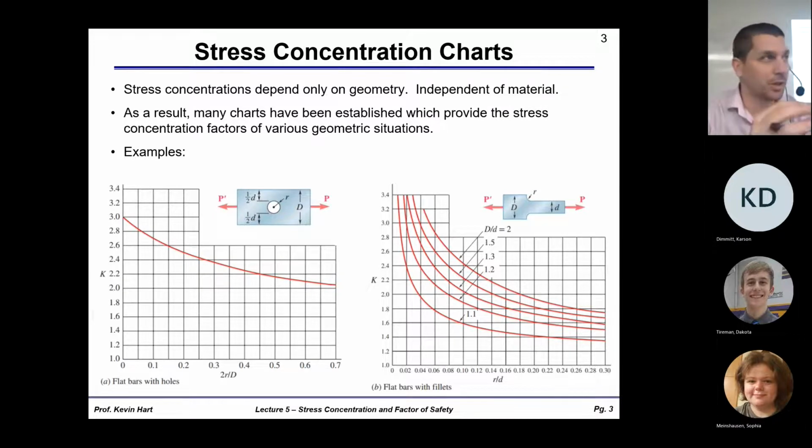All right, so the smaller reduced section, okay? Calculate what the stress would be in this reduced section here, or for the case of the plate with a hole, this reduced section here, and then amplify that particular value. So we saw this for axial loading. In this case, we also have charts like this for torsion and for bending. Any questions about stress concentrations? I think it's a relatively straightforward idea. You just have to be able to read the chart well. Okay.